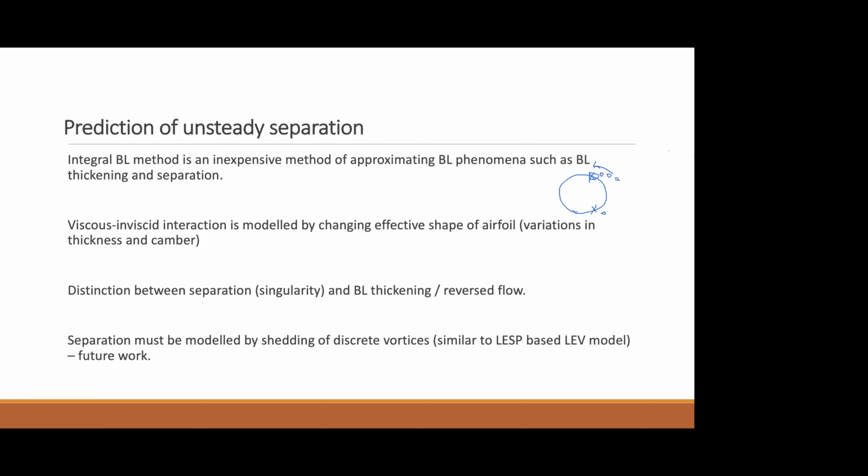On that point, you said integrating beyond the separation point, but what normally happens is recirculation beyond separation. The boundary layer equation is normally a parabolic equation. So with the recirculation region, you really can't integrate in the forward direction beyond the separation point. You need to integrate from the rearward direction. Isn't that the case?